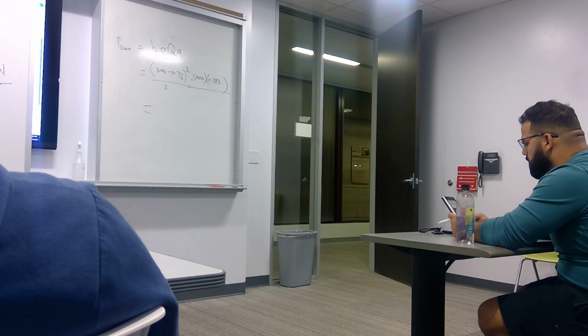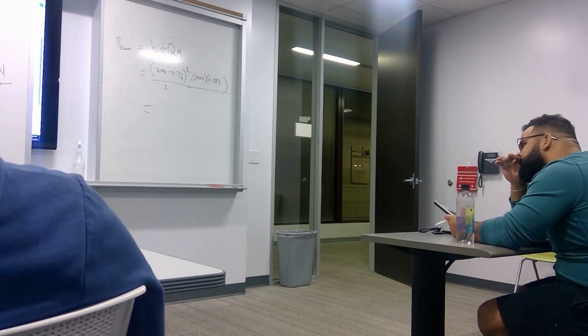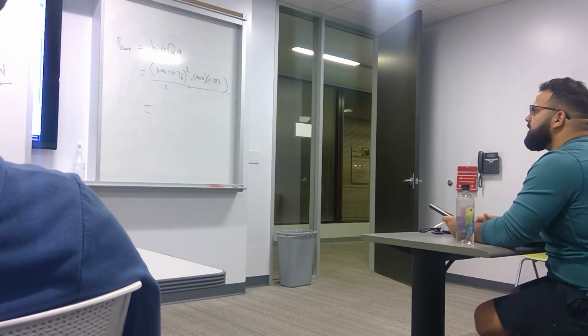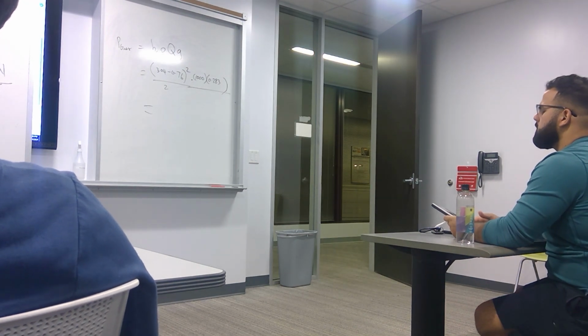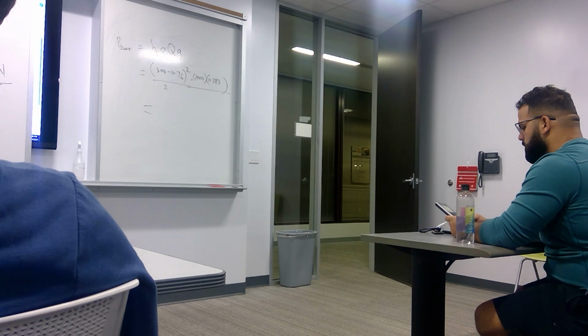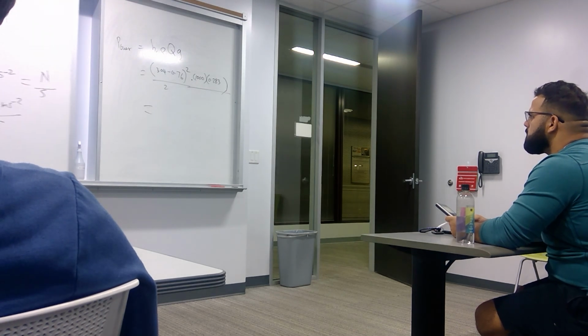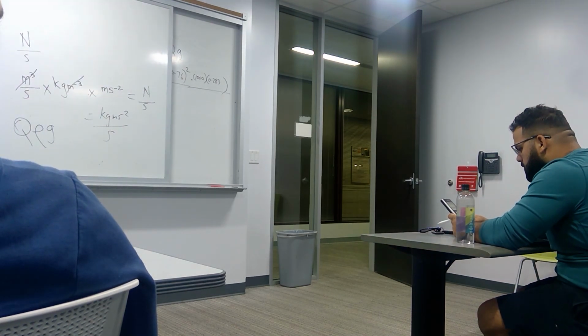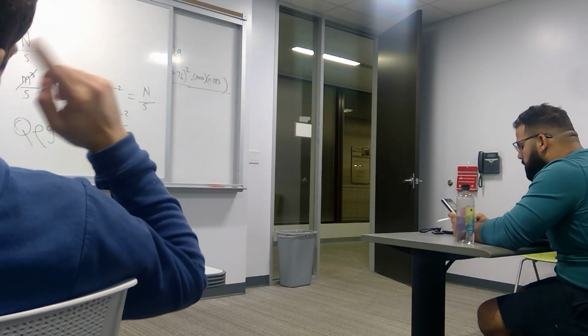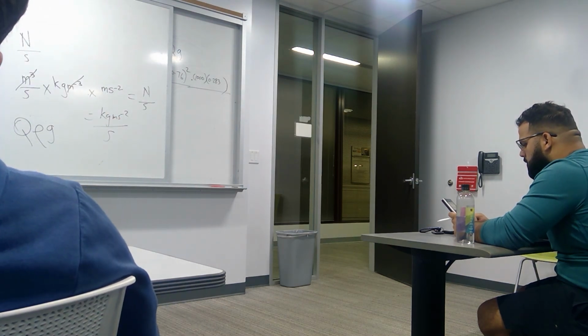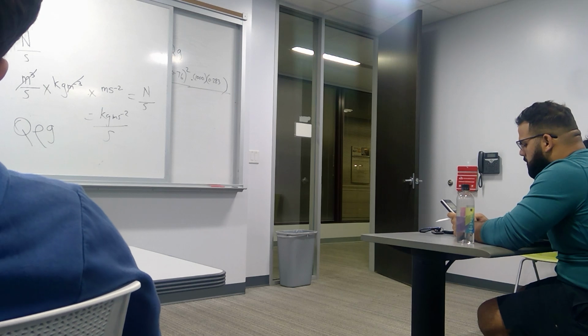Why do you multiply HL? Where did the HL come from? The HL is the loss through the expansion, and so that's the power that we need to provide. They're asking you what is the force needed to force the water through the enlargement? So we need to overcome that loss.